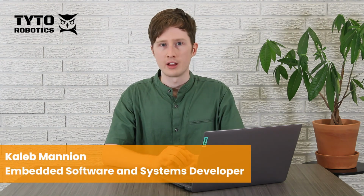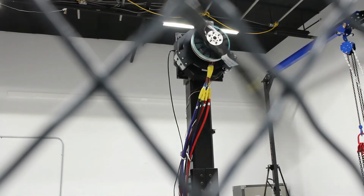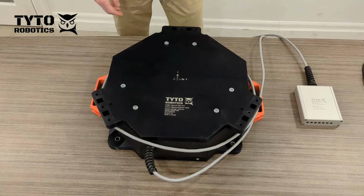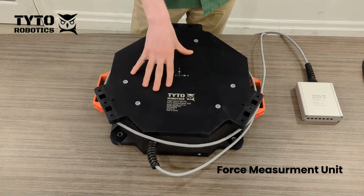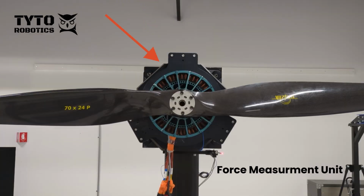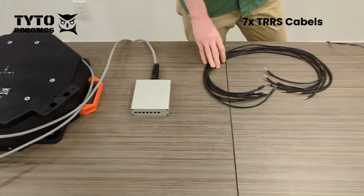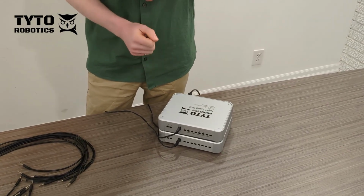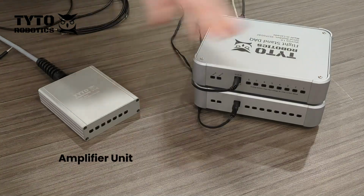In this video, I'll explain how to connect your force measurement unit for the Flight Stand 500 to the Flight Stand software and how to configure it to read thrust and torque. You'll need your force measurement unit, which I have here on this table for ease of demonstration, but for you will likely be mounted to your flight stand, 7 TRRS cables, and the data acquisition unit you'll be using, connected and powered. We're going to start by connecting the amplifier unit to the data acquisition unit.